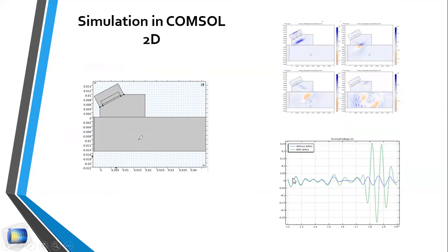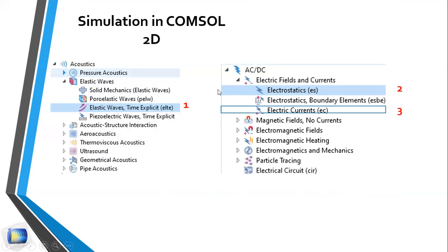By comparing these two signals, with defect and without defect, we can extract details about this defect. But you should consider some things for applying this type of test, I mean the angle of the wedge and piezoelectric.